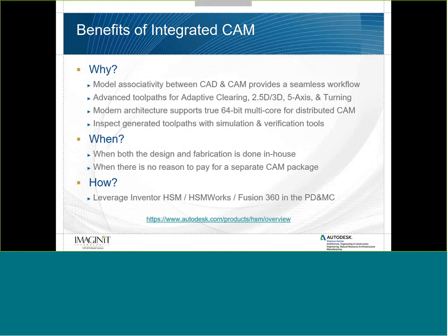But of course, having a modern architecture that supports true 64-bit and multi-core, so that we're able to generate and update our tool paths very quickly. And the ability to inspect generated tool paths with simulation and verification tools to make sure we're not going to collide with the tools or with the parts in the process of machining as we're moving through the milling or turning process.